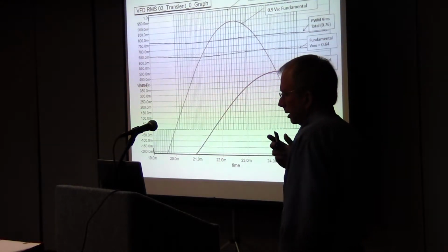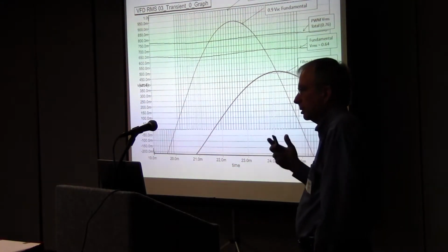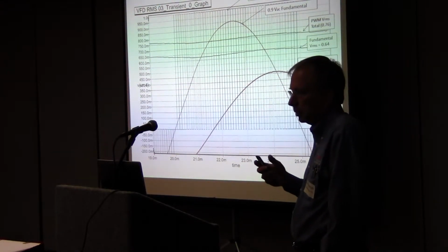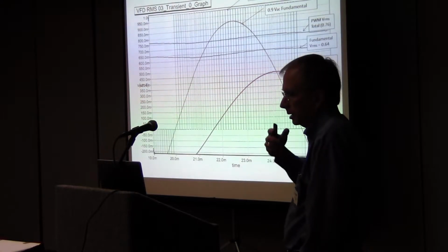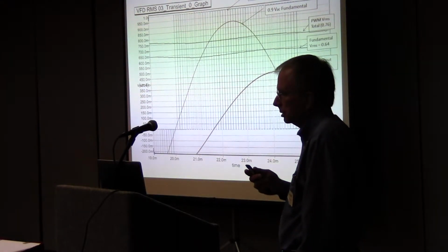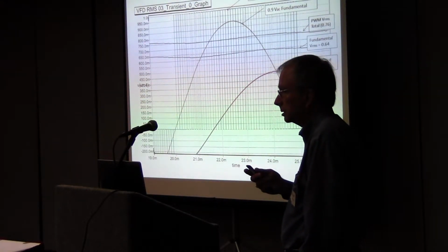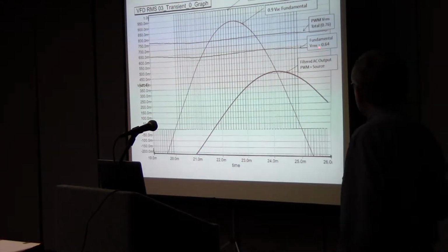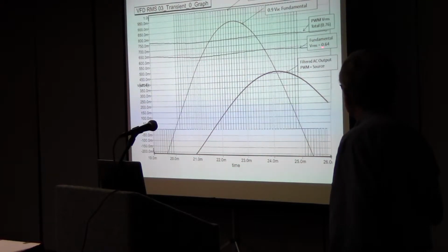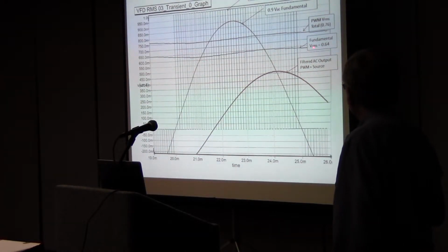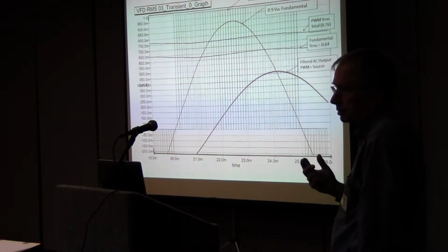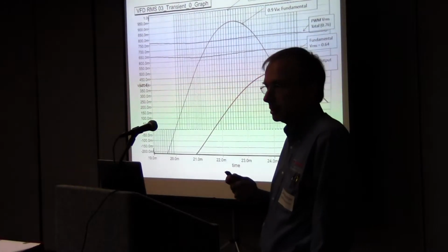I mean, you might, depending on what you're trying to accomplish with your measurements, but if you're interested in what voltage is being applied to the compressor to do work, it's the 60 hertz component in this example. So the 60 hertz, or what I call the fundamental, in this application was only 0.64 volt RMS, where the total power in the PWM waveform was 0.76. So you've got to ask yourself, what do I want to measure? What am I interested in?